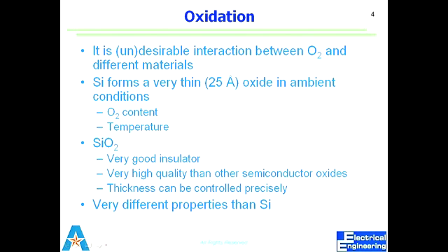So native oxide is good in a sense. It reduces the oxidation rate. Now we have a small layer, and we discussed that oxygen species have to seep through or diffuse through that oxide layer and get to the interface to continue oxidation. So having native oxide is good in a sense. It doesn't let further oxidation occur.